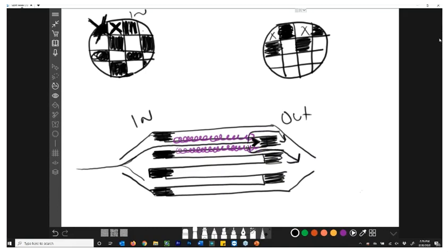So what it's doing is as the exhaust gas comes into this chamber, it's allowing the gas to escape. However, the ash and the soot, the solid substrates, cannot. The solid substrates can't fit through that porous media. Only the gas can. So as you're driving down the highway or using the vehicle, your cell walls are going to start to fill up with ash and soot. We're going to say pink is ash, red is soot. Okay, so we're starting to fill up with ash and soot.